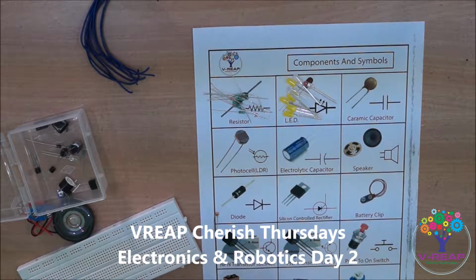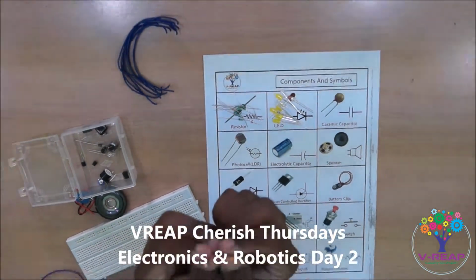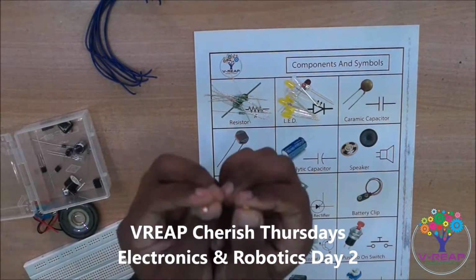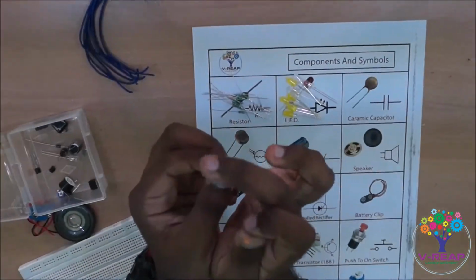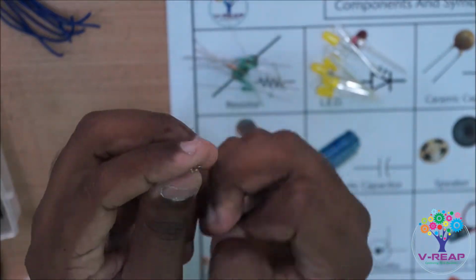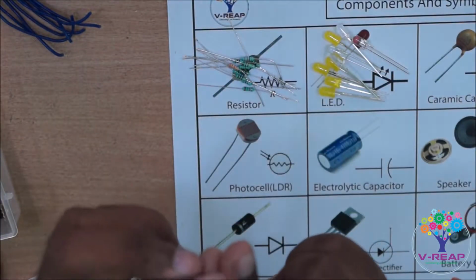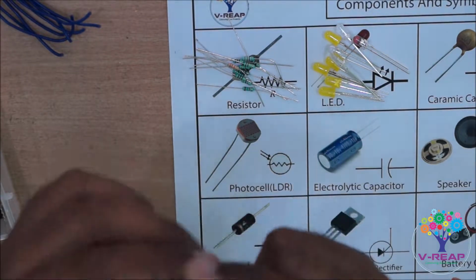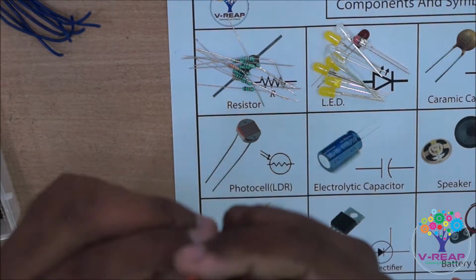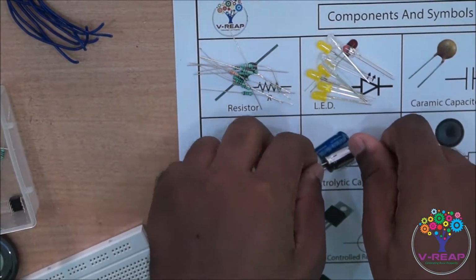The next component is the capacitors. The capacitors are of two types, the ceramic capacitors and the electrolytic capacitors. The electrolytic capacitors have a circular housing. They are cylindrical in shape and have two terminals sticking out of them. Okay, these are electrolytic capacitors. You have 3 electrolytic capacitors in your kit. Place those 3 electrolytic capacitors in their place.